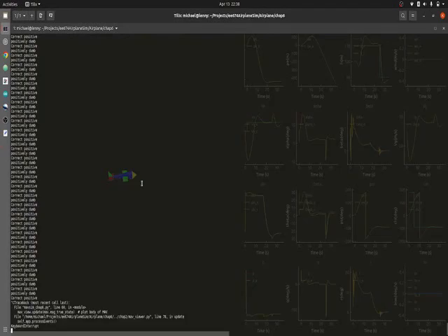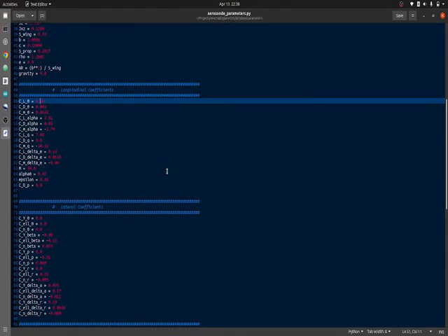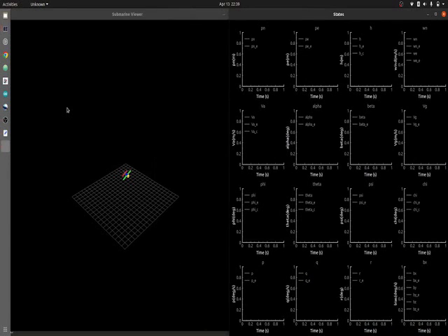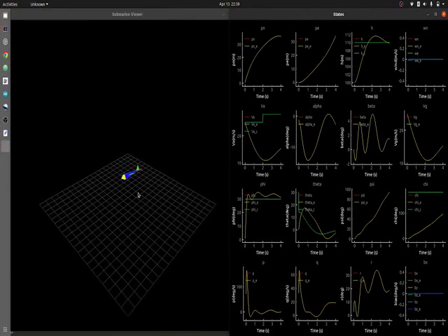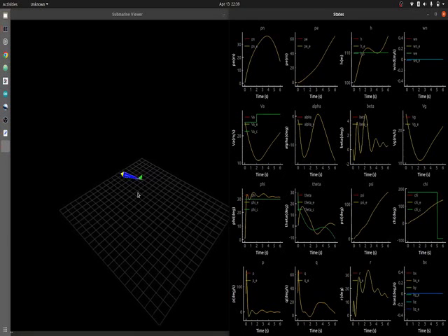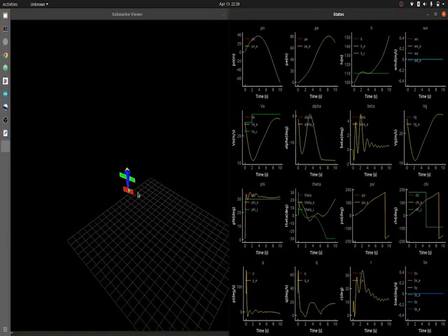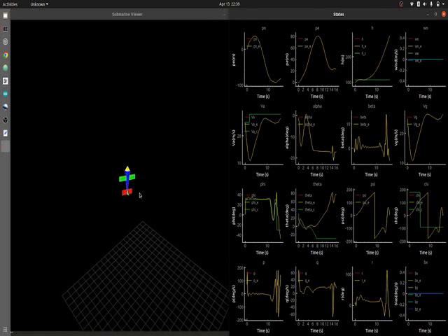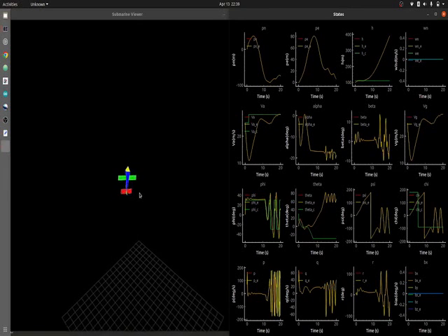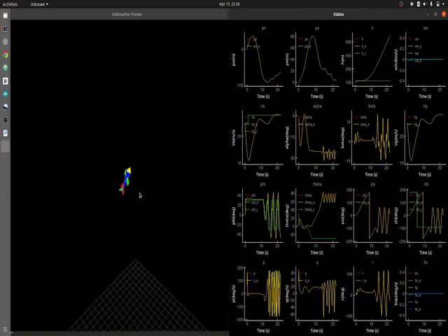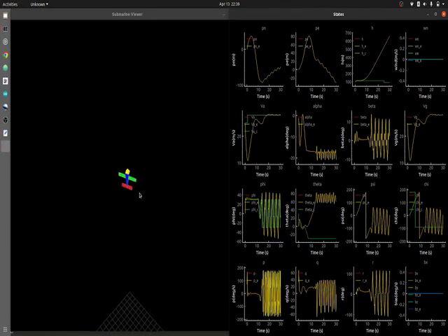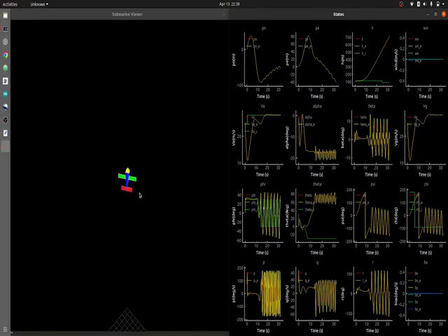Now, if I close this and we change those parameters, let's multiply it by a factor of 10. This is extreme, but hopefully it helps prove that point. You can see it appears functional. It's not falling out of the sky. However, it's also not being very realistic. So this is why it's very important to have accurate aerodynamic coefficients, but it also helps you to understand the impact that poor aerodynamic coefficients could have on a controller for this setup.